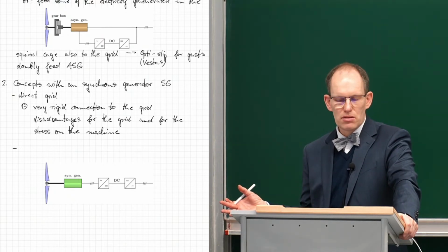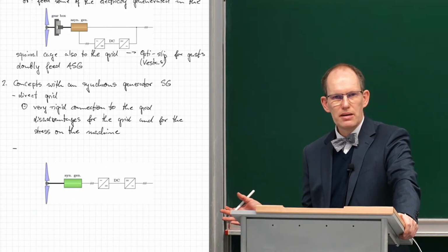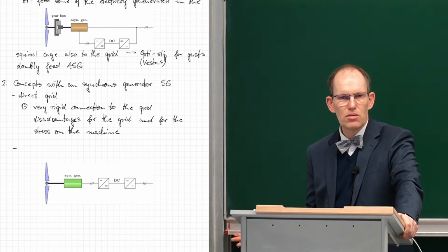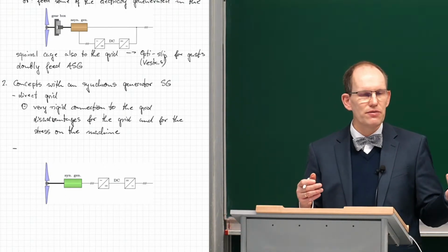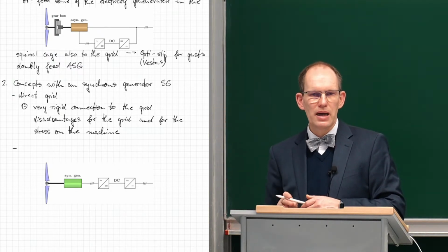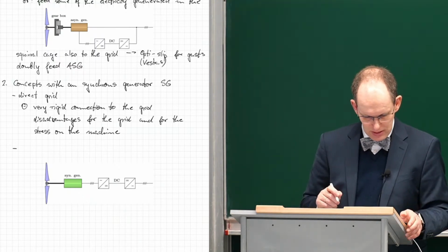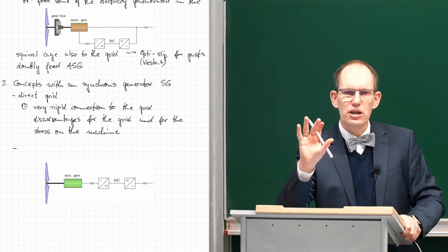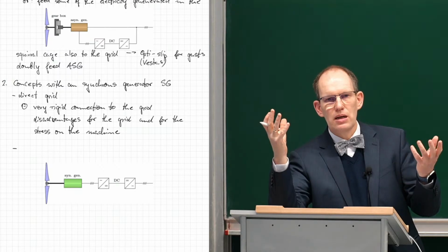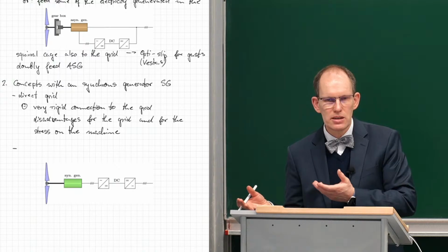And the next thing, similar to what we discussed for the asynchronous machine, would be just to use this synchronous machine, let it run at whichever speed it wants, more or less. And then convert this alternating current on whatever frequency to direct current, and then convert it back to the grid frequency. And we distinguish two combinations which give 4 scenarios.